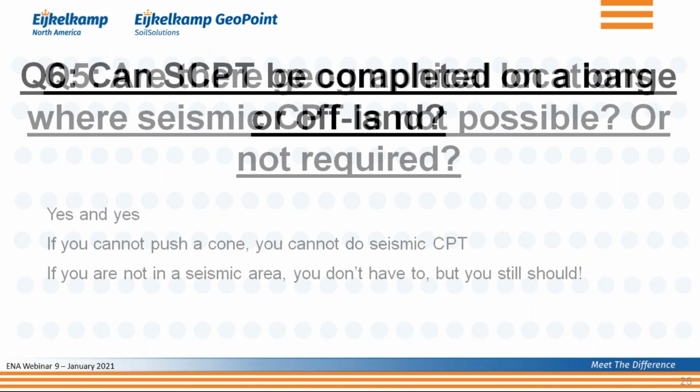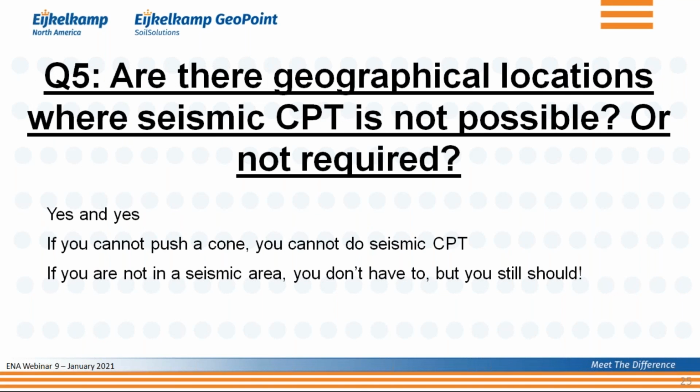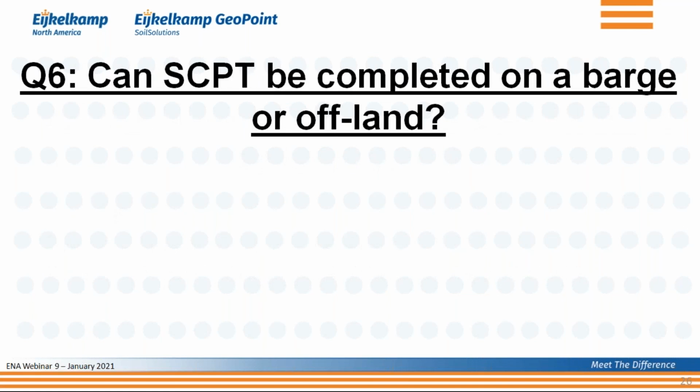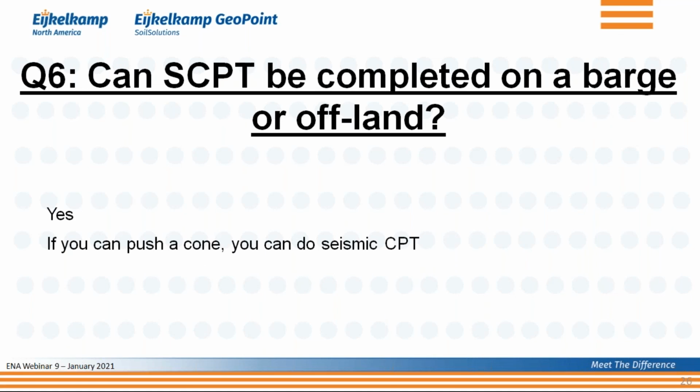Well, in a way, I want to show briefly the previous slide. You say if you cannot push a cone, you cannot do seismic CPT, which then makes it very simple to answer this question. And the answer is, yeah, it can be completed on a barge or off land, because if you can push a cone, you can do seismic CPT. As long as we can push the cone, and we can push a cone off a barge, we can do offshore seismic CPT or offshore CPT.